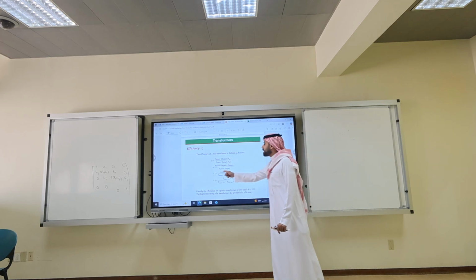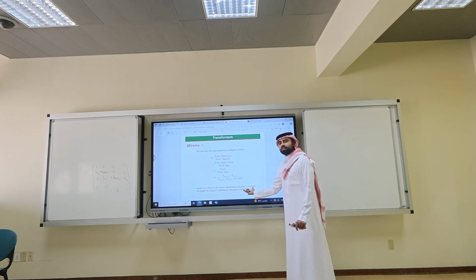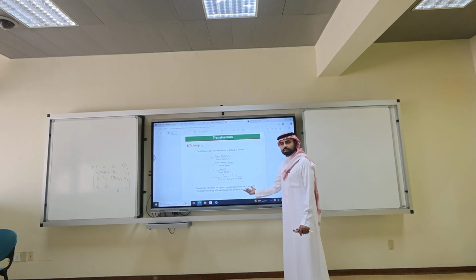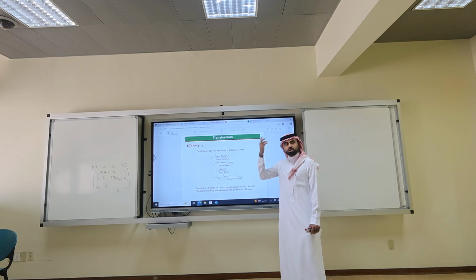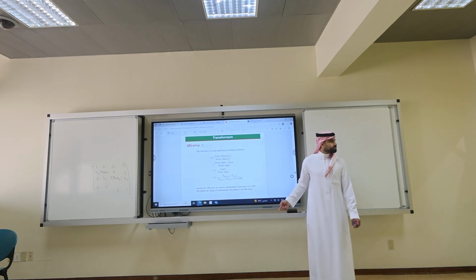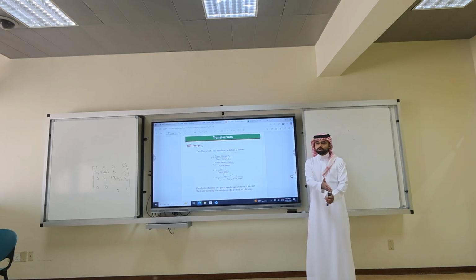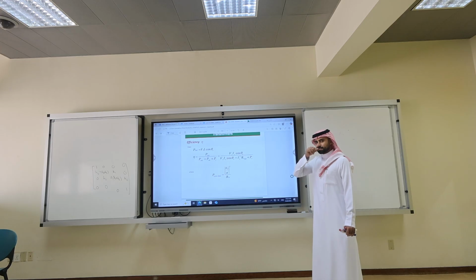So you can use 1 minus losses over input power. If you use this, you can use the circuit. Remember, if I have a transformer of efficiency 80%, is it good or bad? Bad. 90, barely good. 95, good. 99, perfect. Get it? So you need to have a sense of what is good and what is bad. If I have a voltage regulation of a big number, good or bad? Bad. We talk about maybe 8% is bad, 2% is good. Voltage regulation.